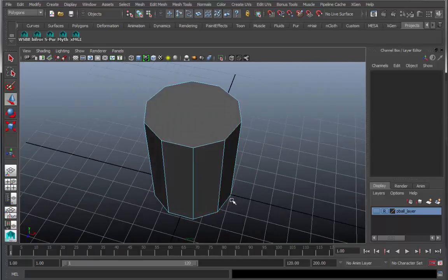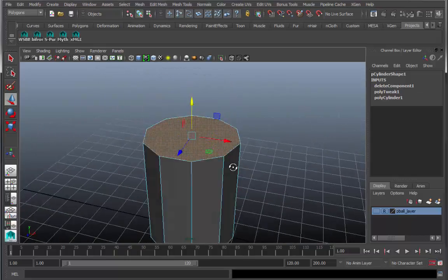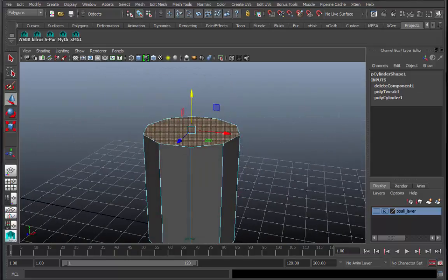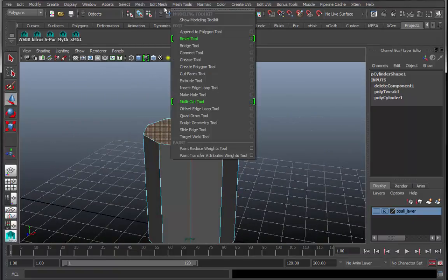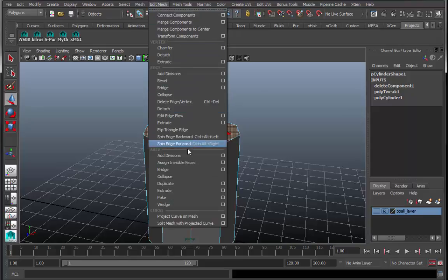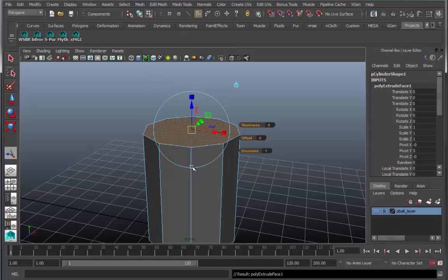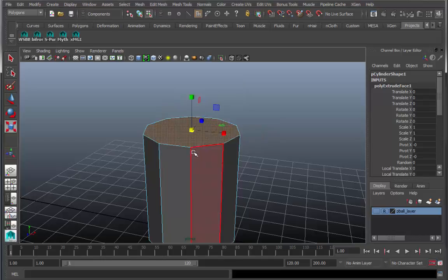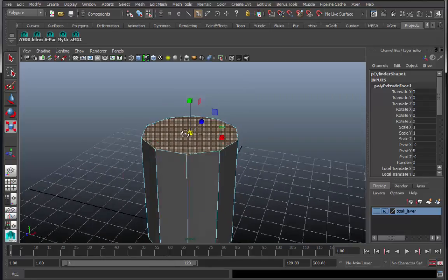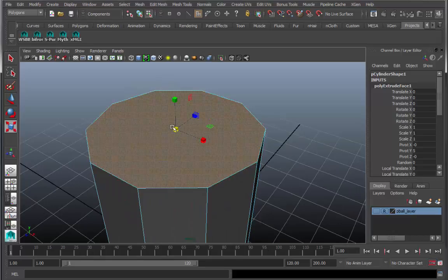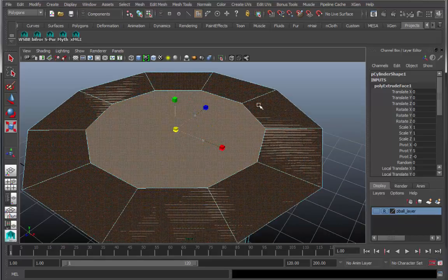So in component mode, let's go here to face, grab the bottom face, just delete it. We don't want it. Grab the top face, and let's get ready to extrude. So come up now to Edit Mesh. We're going to be extruding faces and doing that little trick of don't use the existing controllers. Go instead to Scale. I'm just using the hotkey R, and make very sure you grab that middle controller to make sure you have a uniform scaling outward.